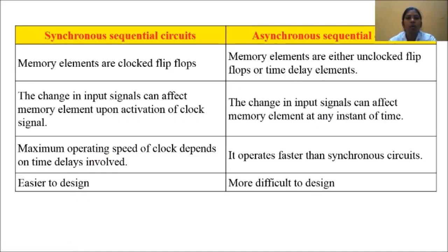We will look into the difference between the synchronous and asynchronous sequential circuit. In a synchronous sequential circuit, the memory elements are clocked flip-flops. Here it is either unclocked flip-flop or time delay elements. In synchronous sequential, the change in input signal will affect the memory element when we activate the clock signal. Here in asynchronous, the change in input can affect the memory element at any time.